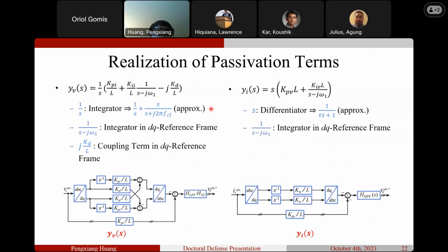And well, the story is not end because the expression I show here cannot be implemented directly in practical model. Like two small examples, one integrator. Can you have an integrator in the system directly use it? No, because if you have an initial value or DC offset, it will be amplified. And DC offset can be introduced by a lot of reasons. We can talk about that later. But if you have an integrator, you have to approximate that by an integrator with a high pass filter.